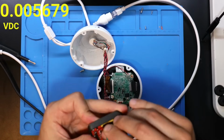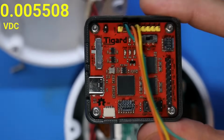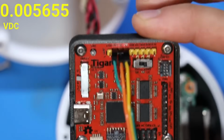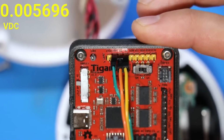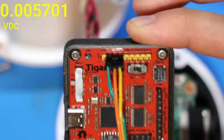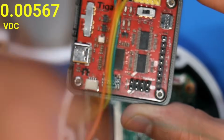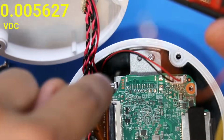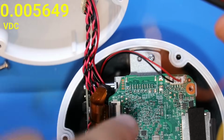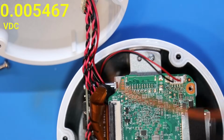All right, so I'm connected up on my little board here. Let's get a good shot of that. To TX, RX, and ground. So green is ground, and yellow is our RX line. I want to connect yellow up to what I think is the transmit pin, which is the second from the bottom pin over here on our board.